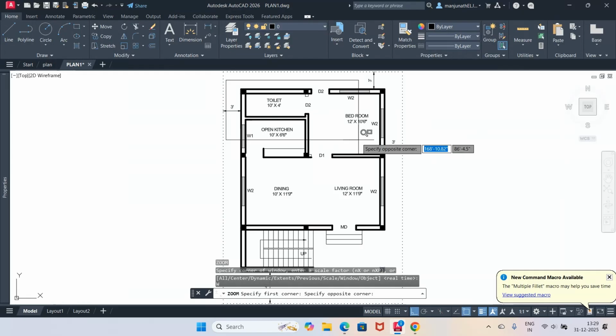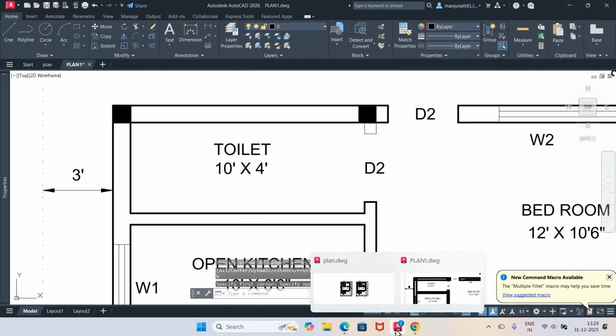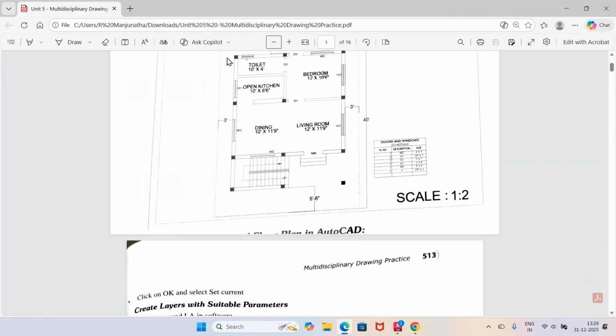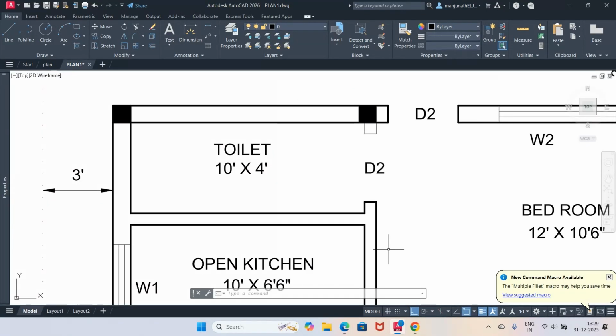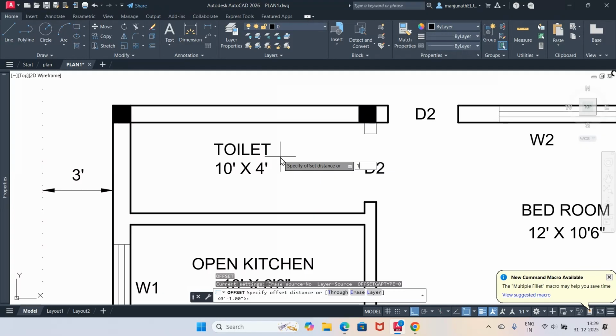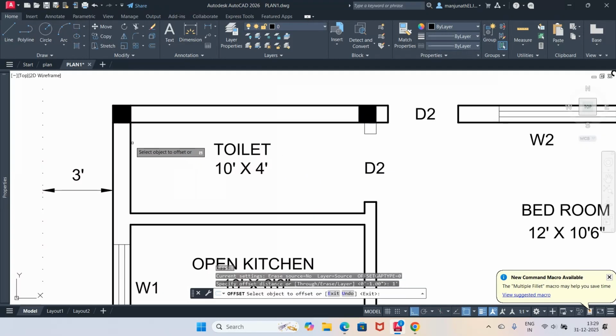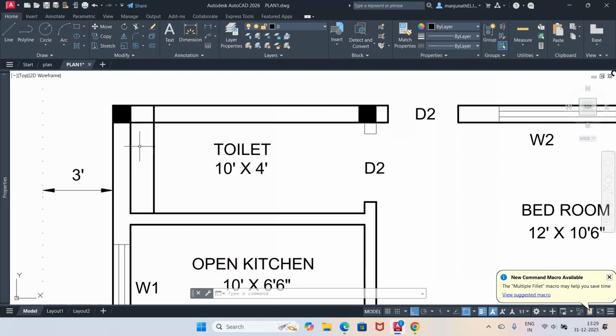So to do that, what is the dimension? I want it from 1 feet from here and take the vent dimension as 2 feet. Okay. So to do that, I will go for offset, take the dimension as 1 feet. See, the problem with this is, once you create this, it is in the layer windows, but actually you're working on layer 0 only, but the entity which you have selected is in a different layer.